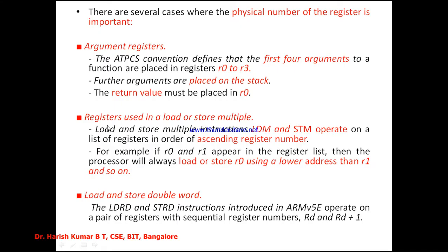The second important case where the physical number of the register is essential is in the load and store multiple instructions. Load multiple, LDM, and store multiple, STM, operate on a list of registers in ascending order of the register number.